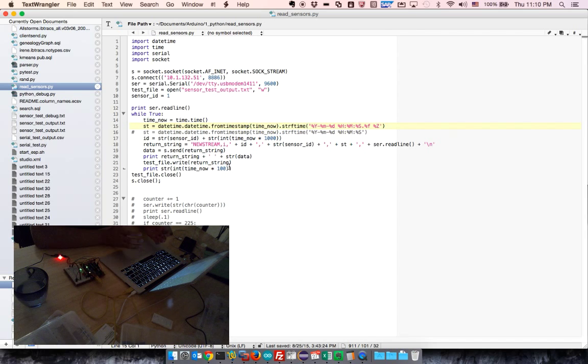Theoretically, we could do all this translation right on the Arduino itself, on that sketch that we've shown, and connect this to SAP's data platform directly. But for processing and for debugging purposes, I chose to have a Python program as a middleman because it also lets me do things like generate data, it lets me do a lot of text manipulation, and since the storage on the Arduino board itself is very limited, I wanted to make sure that if there's going to be any more code going forward, to offload that onto my computer as opposed to burning it on the Arduino itself.